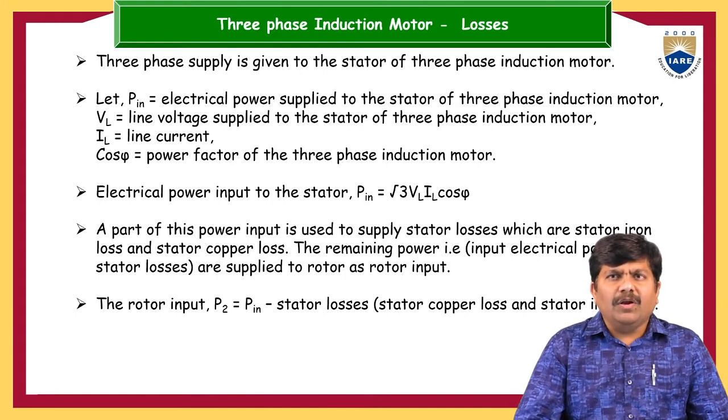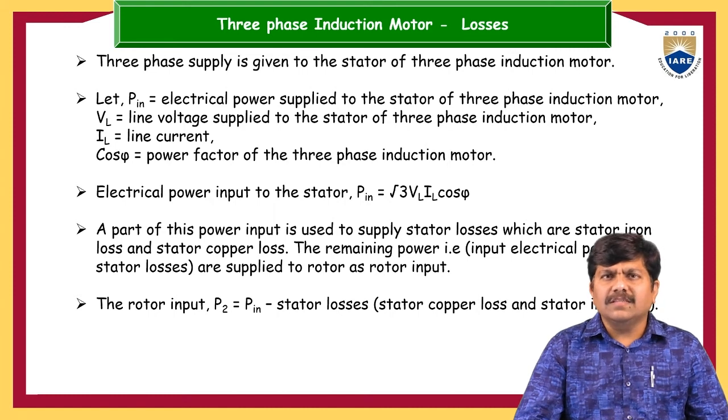So now this is the total electrical power we are giving to the three-phase induction motor, more exactly to the stator frame. Some of it will be utilized to meet the losses, that is converted into losses. The remaining power goes to the rotor as an input.